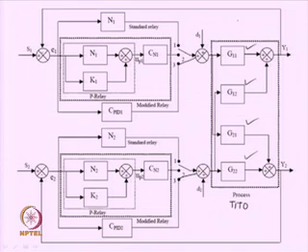So, to set the parameters of the PID controllers that we have got, decentralized PID controllers that we have got for the TITO system, it is first necessary to identify the transfer function models of the dynamics of TITO process, and based on the transfer function model parameters, the parameters of PID controllers are set.